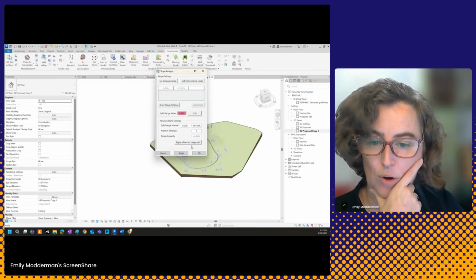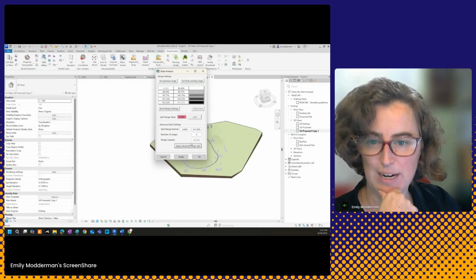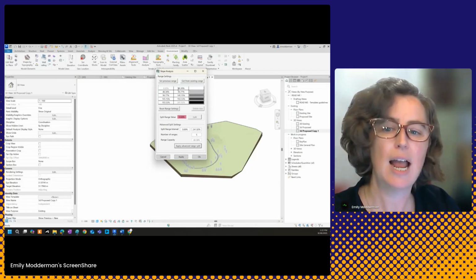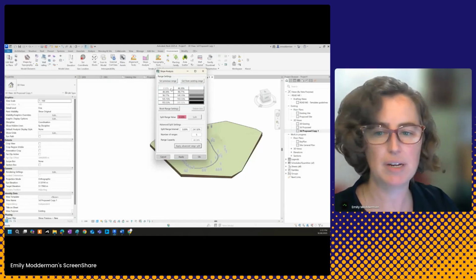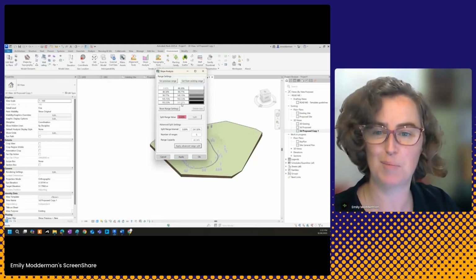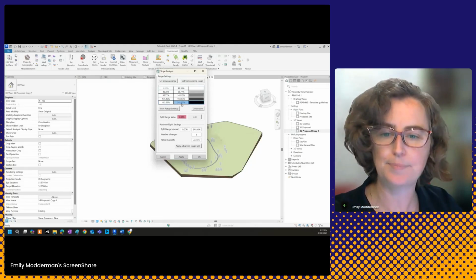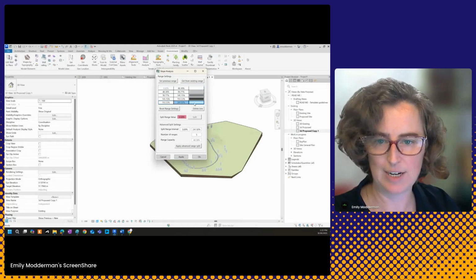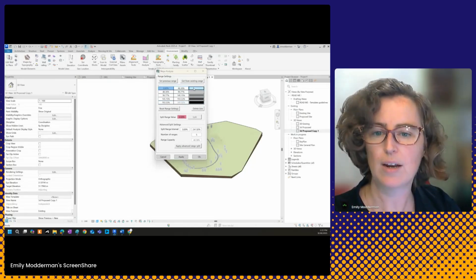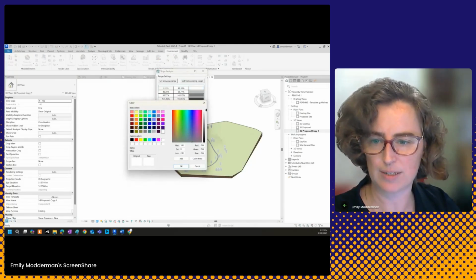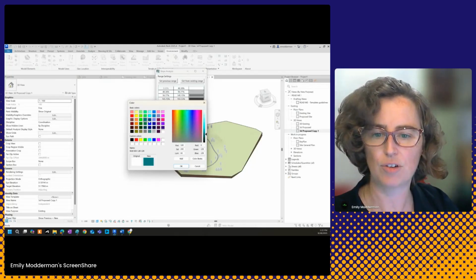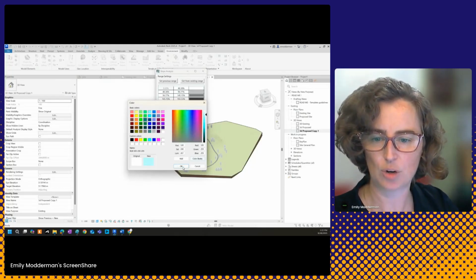Now, I'm going to go with apply advanced range split, and it will basically take me from the lowest, so 0%, and it'll break it up automatically into some chunks between the lowest and the most steep slope of almost 242%. And it'll give me a color range here of a whole bunch of grays. Not ideal. So we can always modify the color range. So if I wanted to pick something in the green or blue range, I can do so. And then, I'm going to start really light.